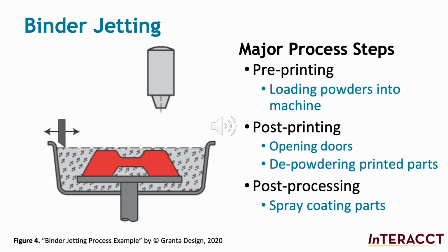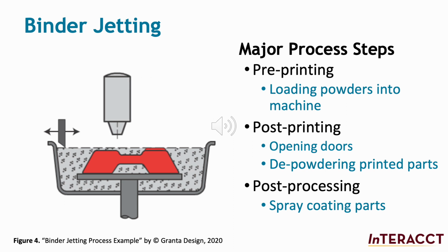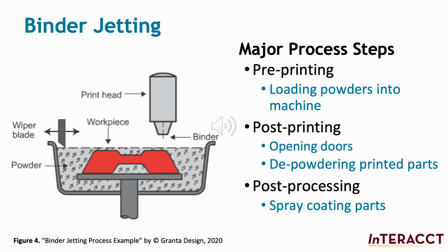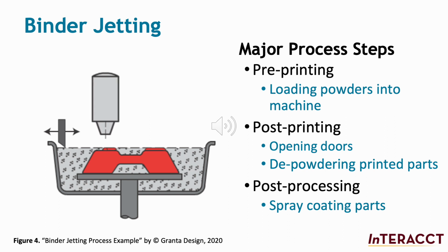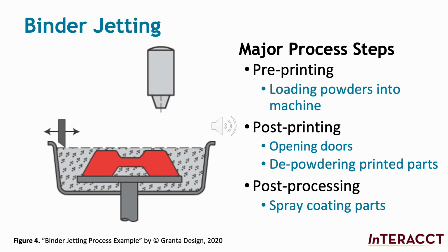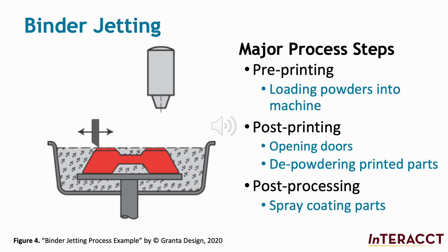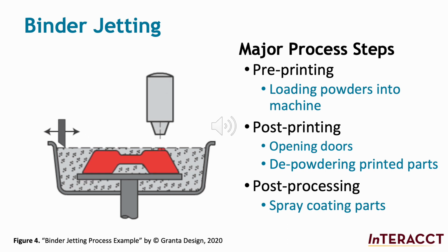A roller rolls a layer of powder from the reservoir onto the build platform, and the printhead applies one layer of binder, and then the binder is initially set by having an infrared lamp array pass over the top. The building platform then lowers, the level of powder in the reservoir is raised up, and the process repeats until all layers have been printed.